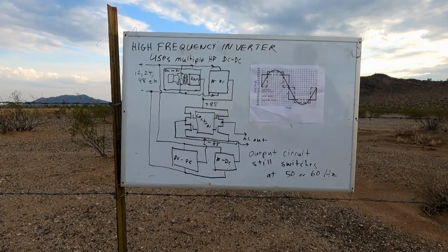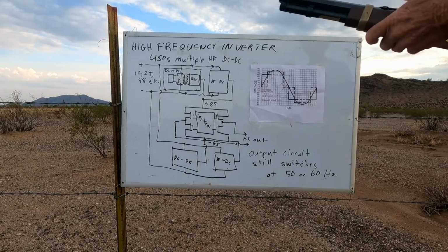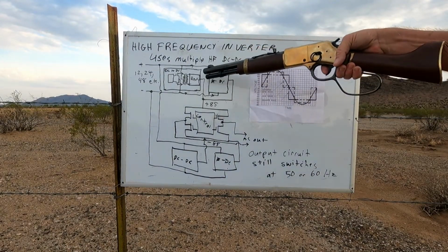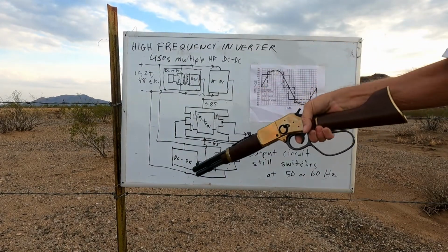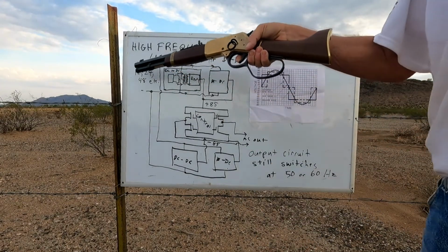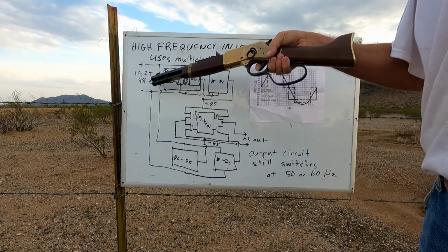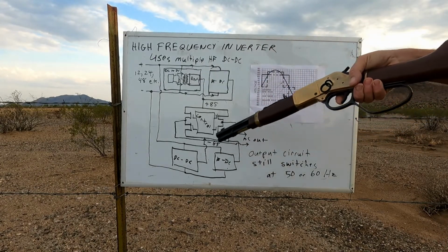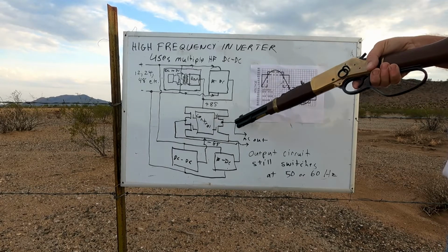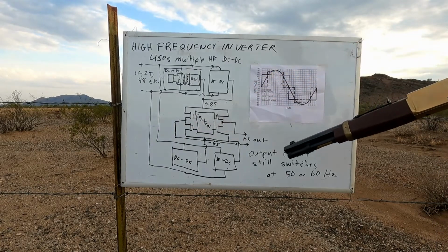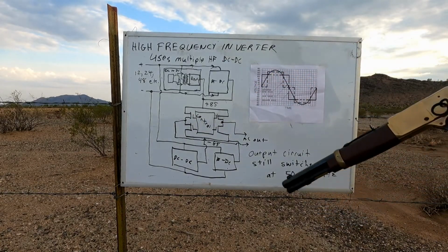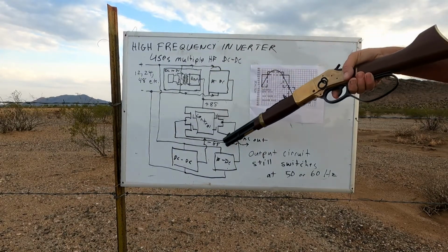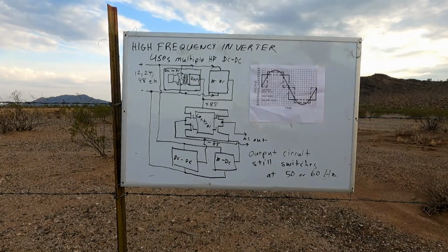So the high frequency inverter uses multiple high frequency DC to DC converters inside of it. Here's what's inside a typical DC to DC converter, and I've shown 4 of them here. They accept the DC input, and those converters then step that DC input up to a higher voltage, which goes to an output switching circuit that operates at that higher voltage. And in this example, we've shown the input voltage converted to a plus 85 and minus 85 volt rail.